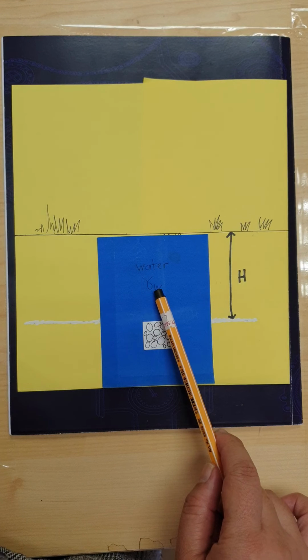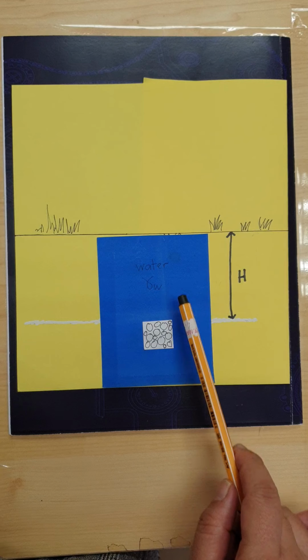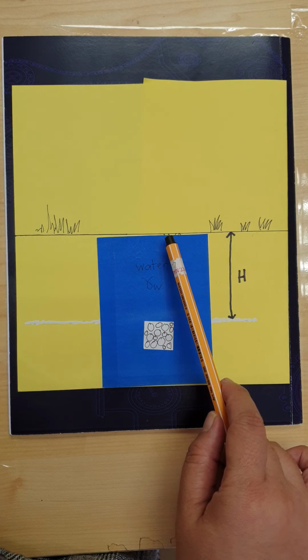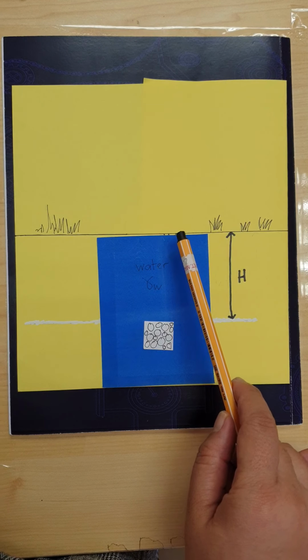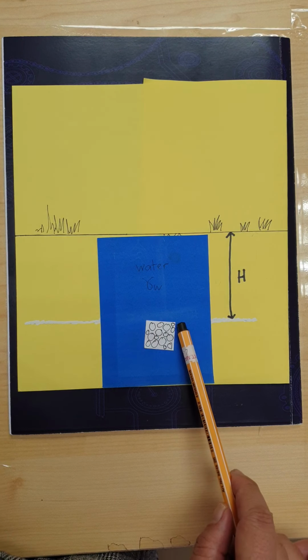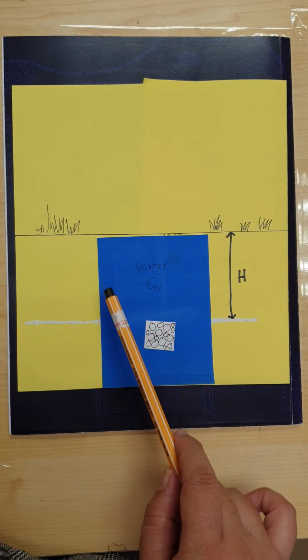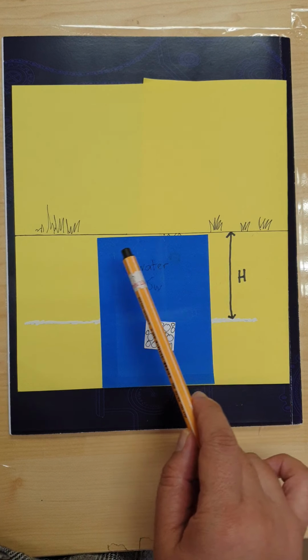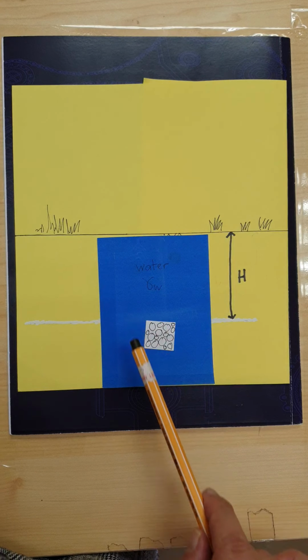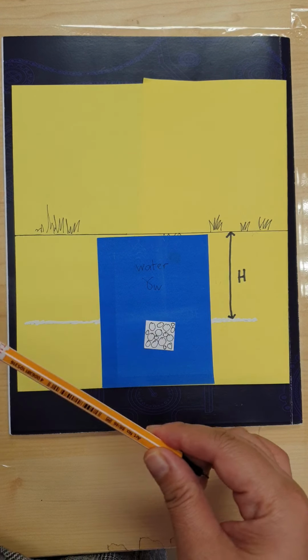The unit weight of water is gamma W, and this soil will experience the weight of water from the ground to this point. At the same time, this whole area has been flooded with water, so the soil in this area is fully saturated soil.